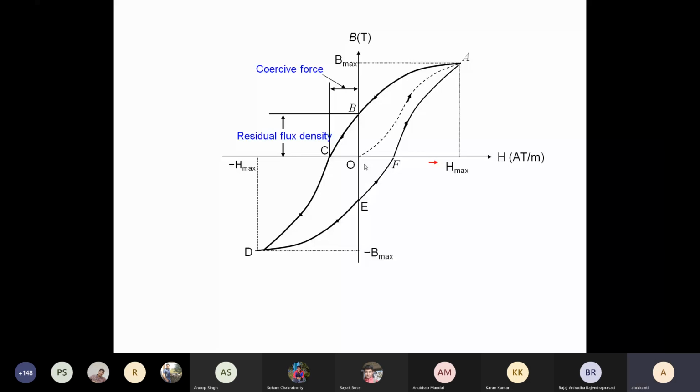So this ferromagnetic material, which is used to make all the electrical equipment, your household fan, any other component you can think of, your tube light choke, everything is basically ferromagnetic material, and they have this type of characteristics. So as H is changed, it will go here, and go here, and this way it will keep on. It will follow this path, and this happens because the supply is AC, so it will track this path to and fro. Okay, so this is known as the hysteresis loop.